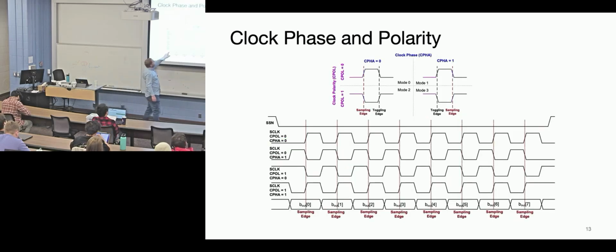These are the 4 clocking modalities. So here, clock polarity and clock phase. And they're showing you here the transition would be in the center of the data. It's just showing you where the clock is. So this would be start high, but rising edge versus falling edge. And that's start low, so rising edge and falling edge. Something to keep track of when you're working out there in the lab and your final projects.